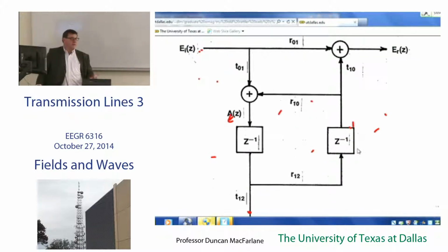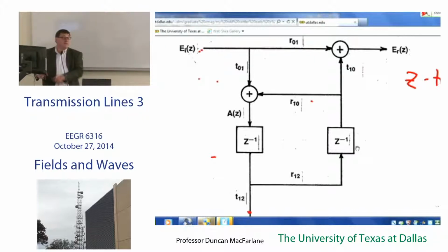Okay? So instead of going into the continuous time frequency domain, I've gone into the discrete time frequency domain. And the reason I was inspired to do that is because of these delta functions coming in and a stream of delta functions coming back out with set delays. That looks to me very much like a digital filter or a discrete time filter instead of a continuous time filter. The advantage is as soon as I use the Z transform, I automatically make use of all the discrete time signal processing packages, notably MATLAB.